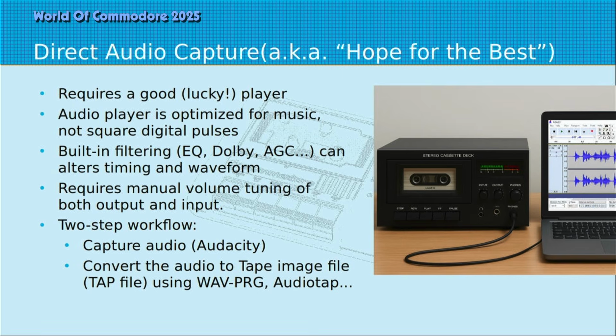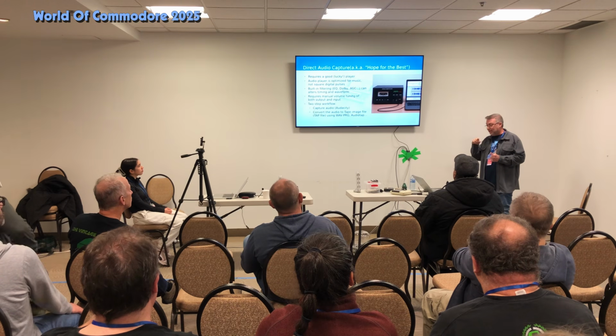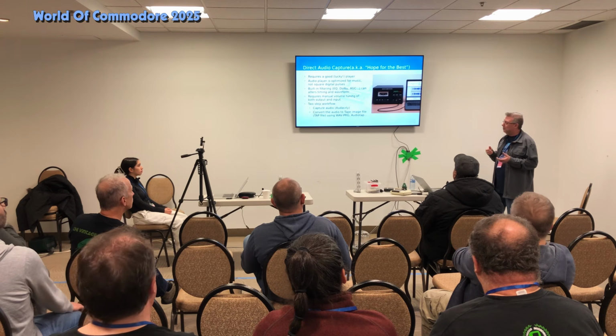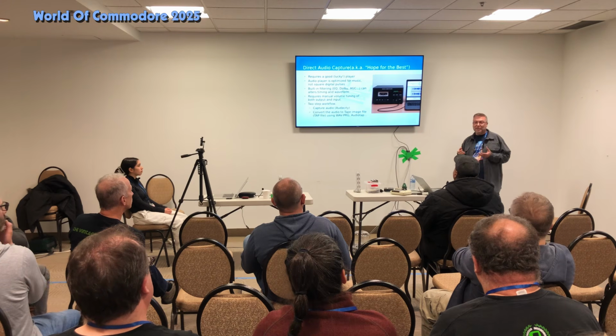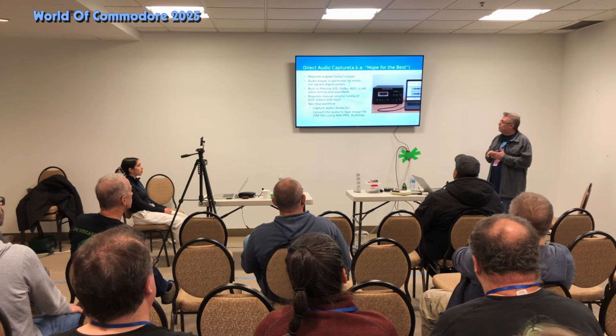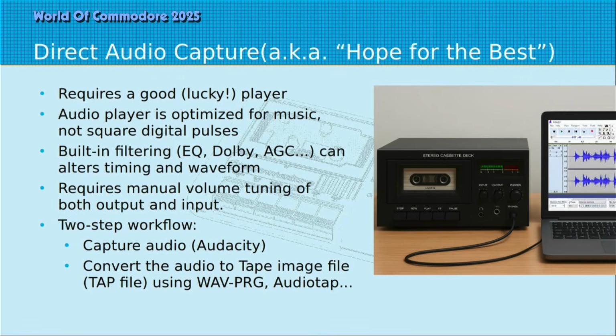You just need a good tape deck, a good tape player that you connect to your PC, and you record the signal. But as I was mentioning, the signal on the tape is a square pulse, it's not audio. Tape decks designed for music have all kinds of filtering, equalizer, Dolby, AGC, all that stuff that can alter the timing and the waveform a little bit. So depending on your mileage, it can work or not. It also requires some tuning of the volume at the output and the input to make sure the signal is good.